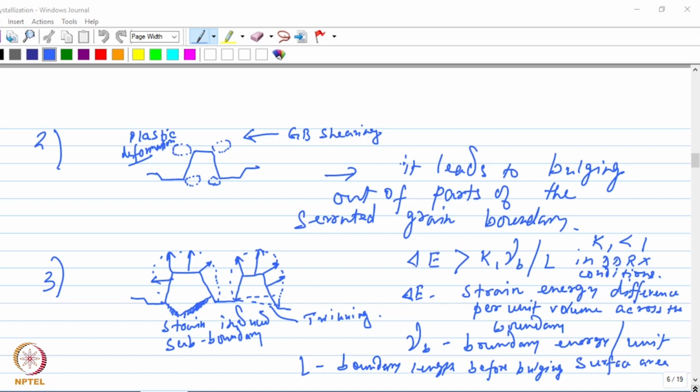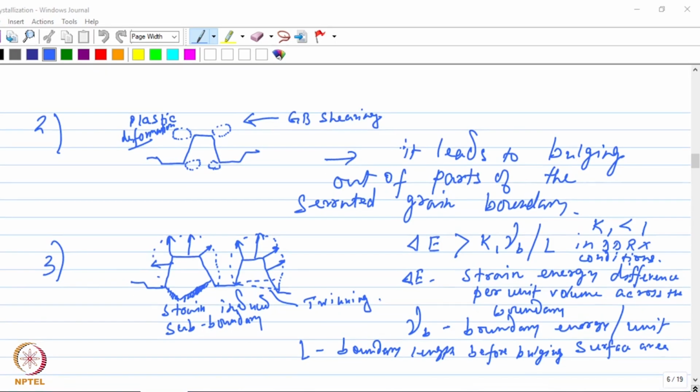We have also seen that the boundaries which form around this bulge, or the nucleus which forms out of the bulge, will depend on the Zener-Hollomon parameter. For high values of the Zener-Hollomon parameter, the boundaries will be low angle boundaries, while for low values of Z, twin boundaries will be generated.